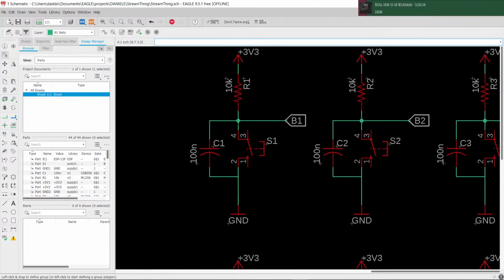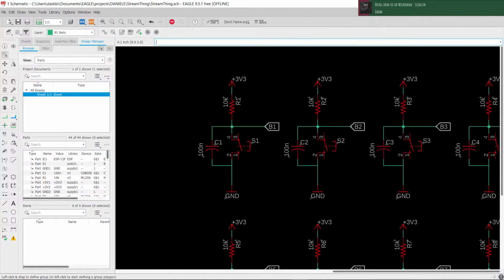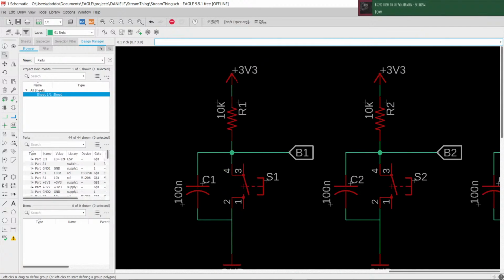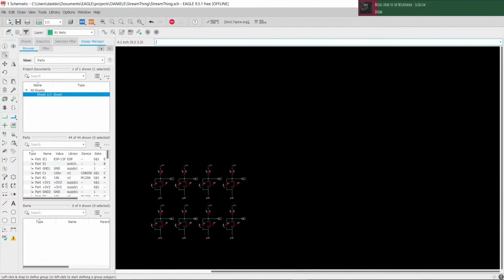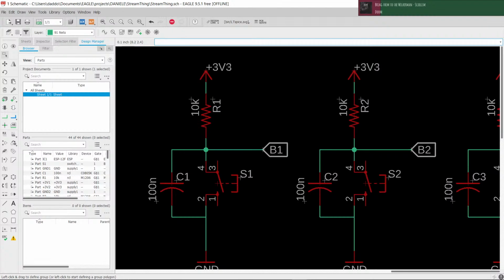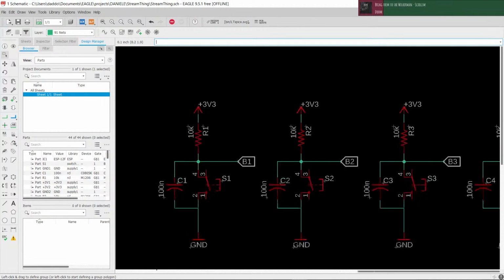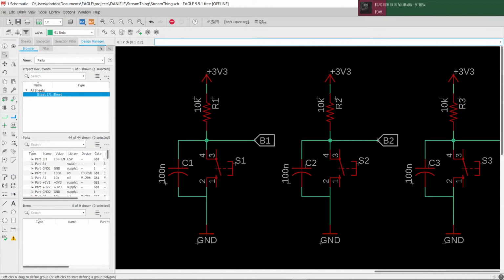Okay, so I've been explaining to someone that I have been doing the designing, and these are buttons to use with the thing. And yesterday I discovered that not every pin on the ESP12F can do pull-up resistors, and I don't know why, and it has been bothering me. So I decided to use external pull-up resistors.